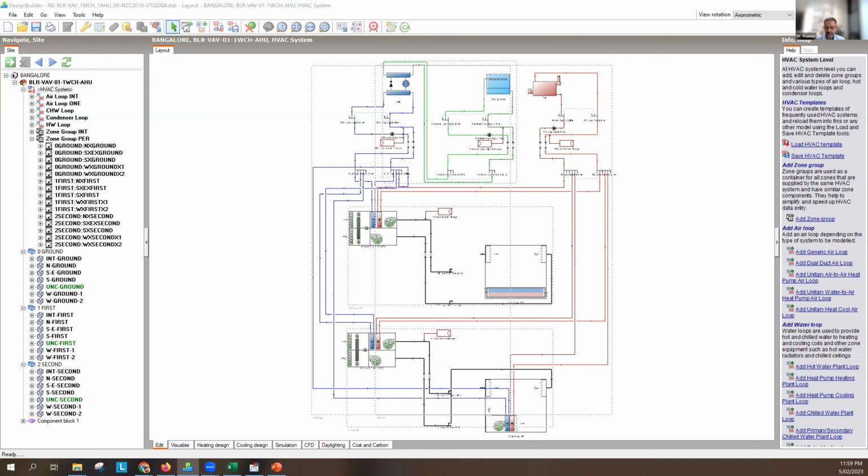Now, we're going off slightly on a different track, but very quickly, the industry has responded by finding some new refrigerants which have lower global warming potential. So they're using something called R32. Okay. Global warming potential is not 1900, but it is 600 kilograms CO2. Big difference, a third, but still pretty high. But the problem with R32 is that it has higher flammability.